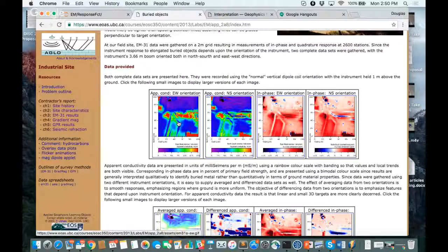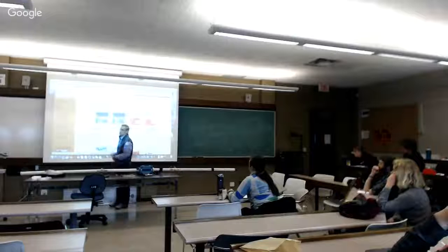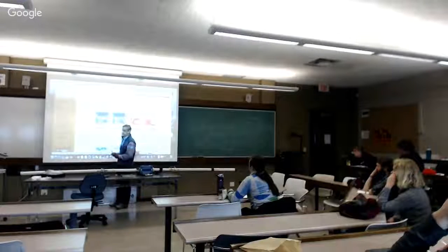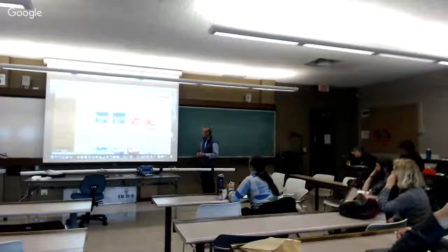At the same time, sometimes just a quick diagnostic survey with a piece of geophysical equipment can tell you a huge amount, right? So you get these two maps, which you can acquire in a day, and you start to find locations of conductors. You can find wires, and if you've got any indication that this may have been a hydrocarbon here, you'd have been able to do that. So really, of all of the techniques that we used for this, this EM31 was essentially the most effective.